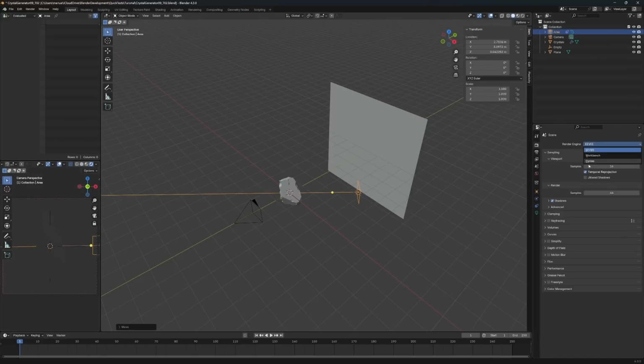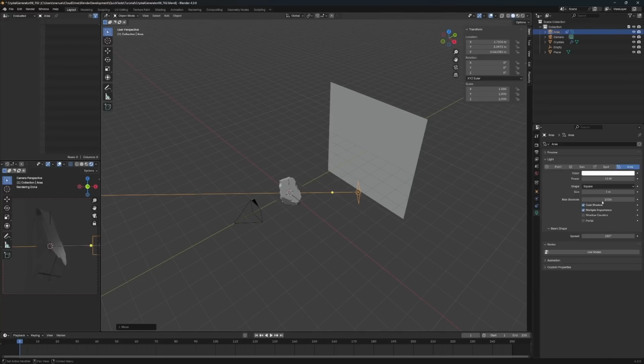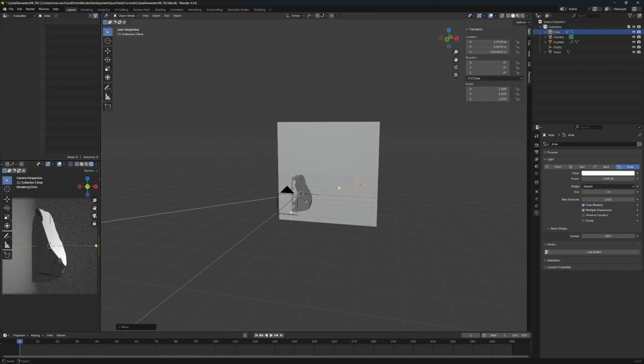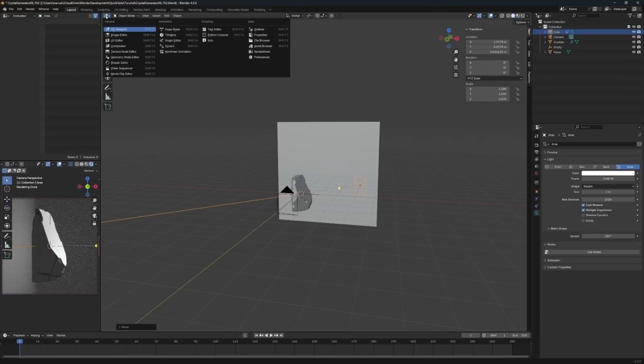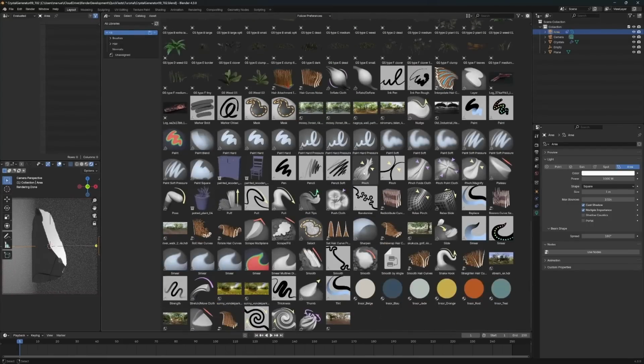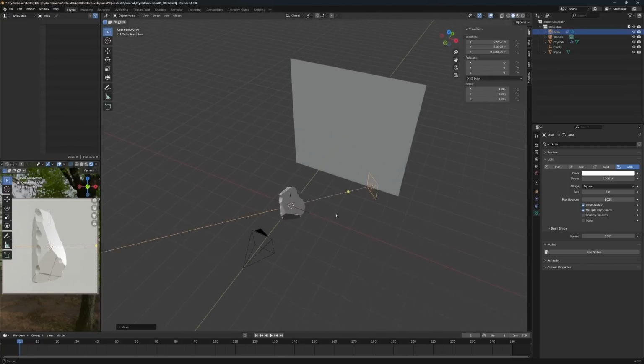If we quickly switch to Cycles, we get a crystal that is lit from the side. Give this light a lot more power, say 1000, and put it somewhere here. And then for the ambient, I want to use an HDR that I got in my asset browser. I downloaded it from Polyhaven, and I want to use this Nagoya wall path. You can use it by just dragging and dropping it there, and that gives a nice ambient, as you can see. So that is my rendering setup.